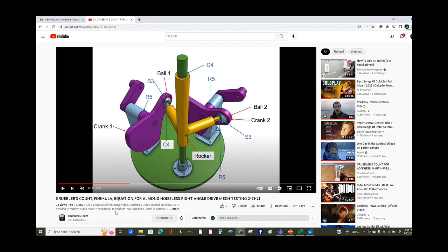Another thing I'd like to share with you: do you see this little mechanism right here? Does anyone know what it is? It's an oil pump rig. Right. And as I'm running it here, you can see this is like a ballast weight, and this is what it does all day. But they're not using the right joints, because if you don't mount these perfectly in line, they have revolute joints everywhere, and it can bind.